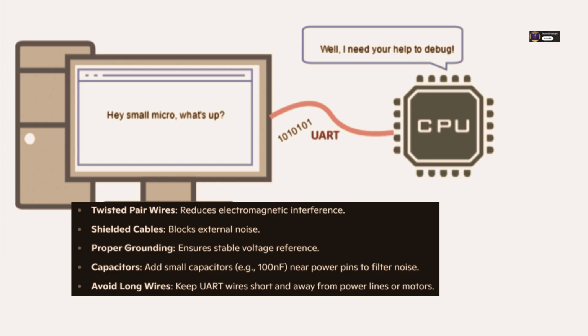2. Connect the adapter's GND pin to the microcontroller's GND. 3. Connect the adapter's TX pin to the microcontroller's RX pin. 4. Connect the adapter's RX pin to the microcontroller's TX pin. Remember the crossover.